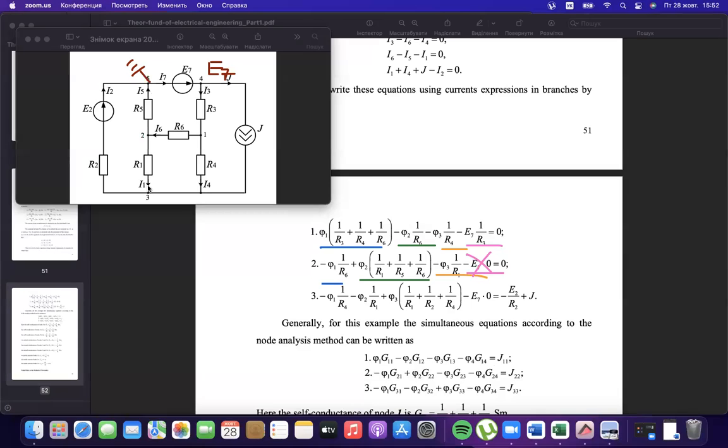the last equation, number 3: self-conductance of this point in all directions, self-conductance positive, 0 conductance from the source, negative conductance with point number 1, negative conductance with point number 2, and with the source, with 0 voltage because of grounding.